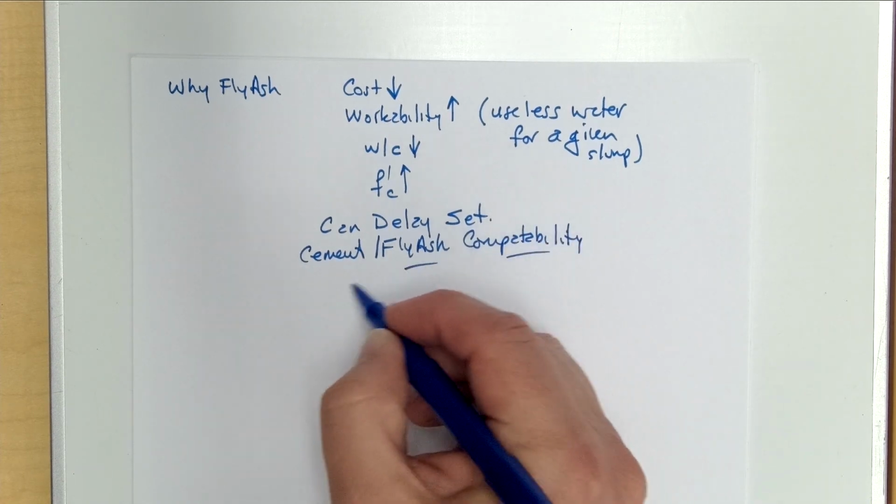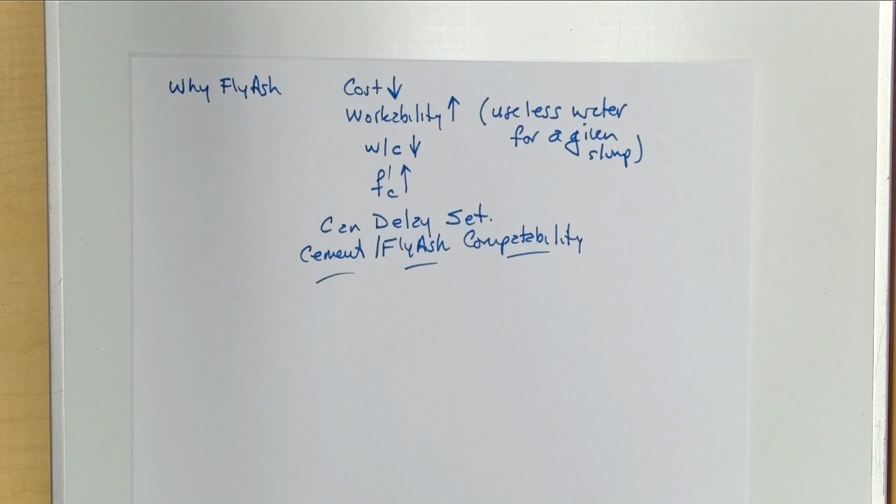Okay, so that's important. And it's generally true. Fly ash is not manufactured, right? It's a waste. It's generated when we burn coal. And so for a while we had tons of it everywhere. There's a big problem now. We don't burn as much coal. And when we don't burn as much coal, we don't generate as much fly ash. And a lot of problems that we solved in concrete mixtures with fly ash are coming back to say, you thought I was solved, but looks like you ran out of fly ash.